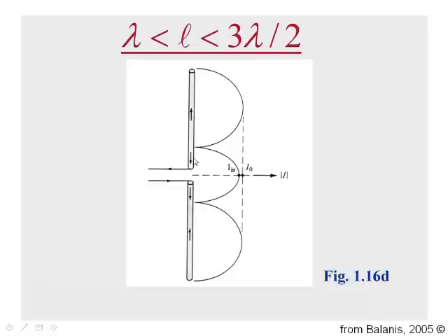Whenever you have currents reversing as such, these currents will tend to radiate, and these currents will then null out the contributions of those currents to some extent. How much? All depends upon what the integral comes out to be. So we'll have to work out the radiation integrals and determine exactly how much as we go along.